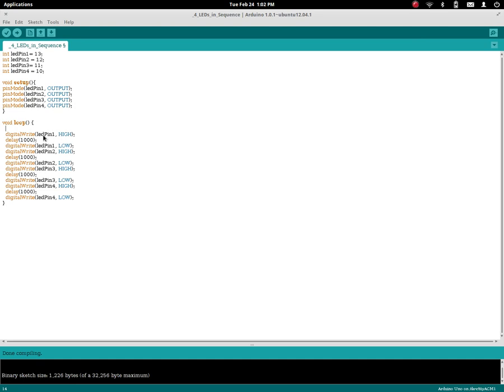Okay, so now we have a comma here, and then we have this HIGH. What this HIGH is saying is we're going to turn the output on high. So if it's an LED, we're going to turn that LED on. If it's a buzzer, it's going to go bzzz, you know. And if it's a servo, there's other things you have to do for a servo. You can look at the servo code on my servo video if you're really curious about servos. But look in the code that you download from the website for that. So that's HIGH. And then we're going to delay.